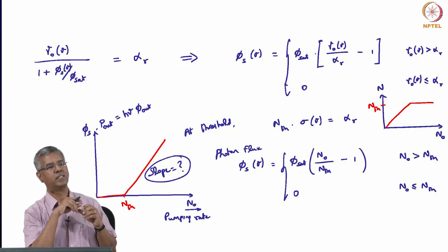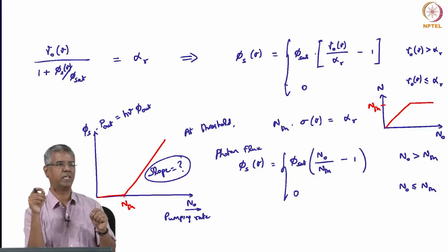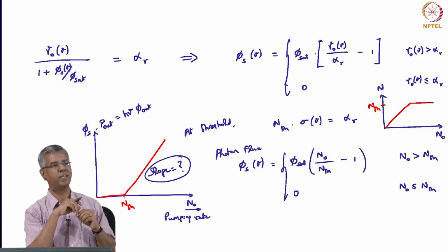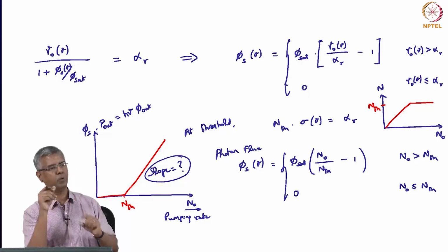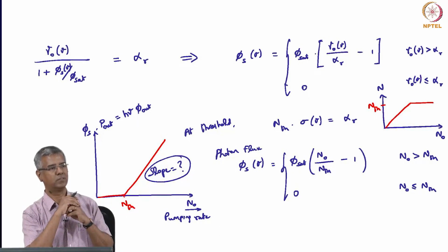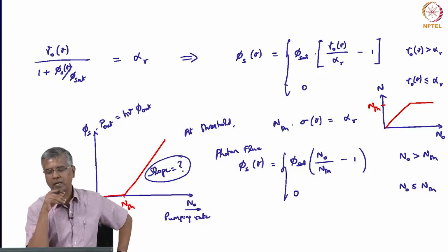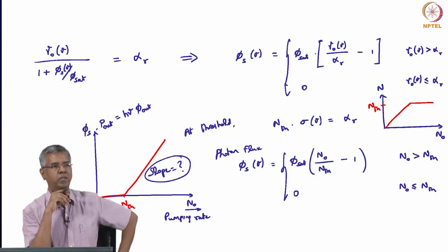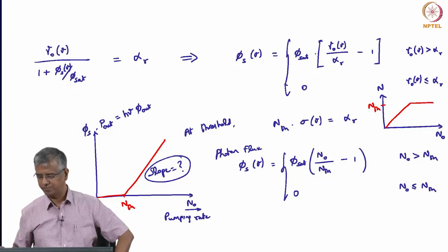dielectric thin film layers such that one stack can give you, let us say, 50% reflectivity at 1 micron wavelength. Okay, let us say 1 micron is your signal wavelength, and let us say 0.8 micron is your pump wavelength. You can put another stack on top of that, which will reflect all the pump photons. Okay, so these mirrors are typically dielectric thin film filters, and you can make the mirrors such that they provide different reflectivities at different wavelengths.